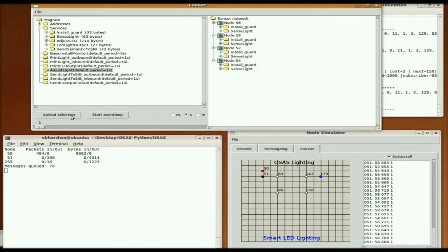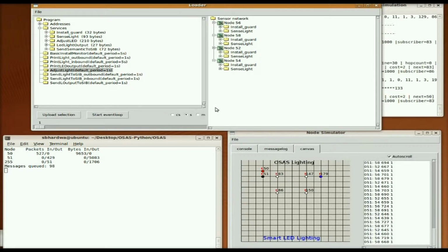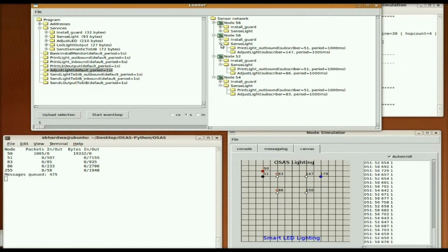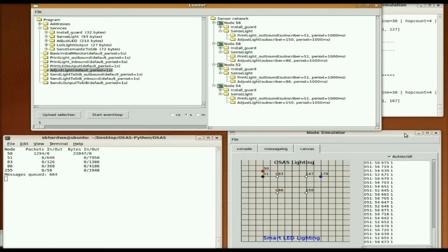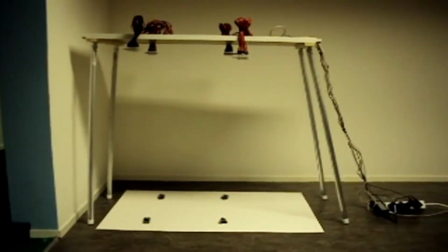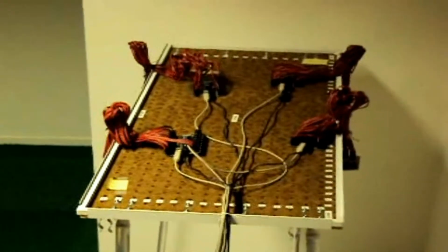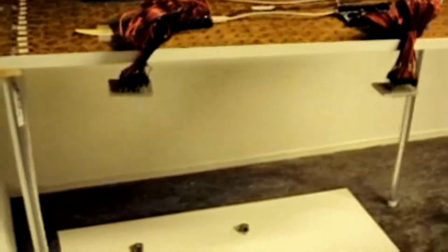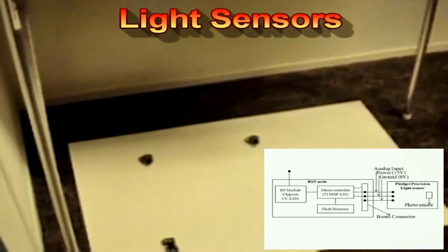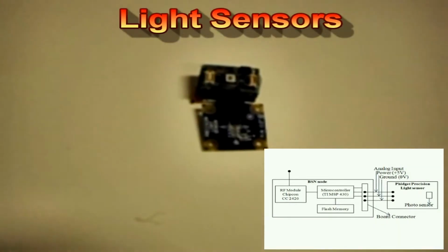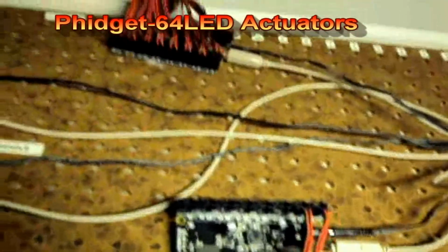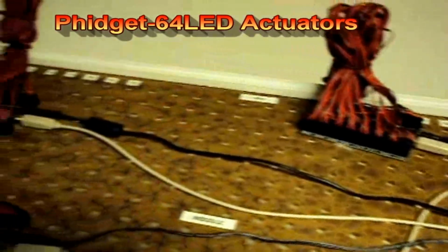The Light KP is connected with the wireless light sensor network based on the IEEE 802.15.4 protocol. It is also connected with a group of distributed LED luminaries over the USB interface. The light sensors are placed under each luminary, and the light intensity is reported to the Light KP periodically. This information is used to generate light output commands from the Light KP to the actuators of the LED luminaries.